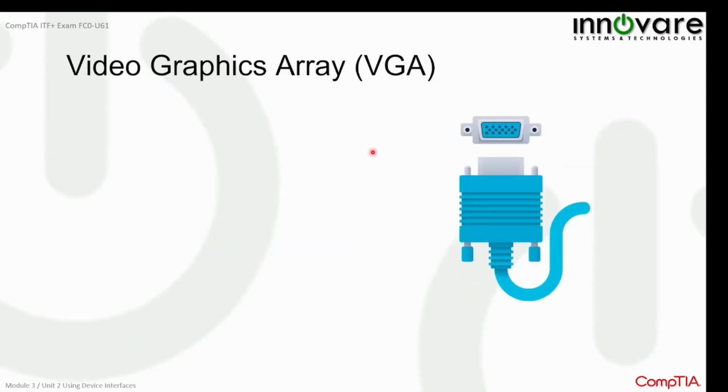So ito yung sinasabi ko na I was trying to explain as well earlier, one of the analog na interface for monitor. We always call this VGA, which stands for Video Graphics Array. And you can tell from the shape of the interface, ito yung front side. And then, you can see these retaining screws, to secure the connection para maging firm at hindi madaling matanggal. So you can tell from here, there are 15 pins and it's always colored blue. If it is not colored blue, it is not a VGA cable because meron din mga ganyang similar na connectors, but it is used for a different application.